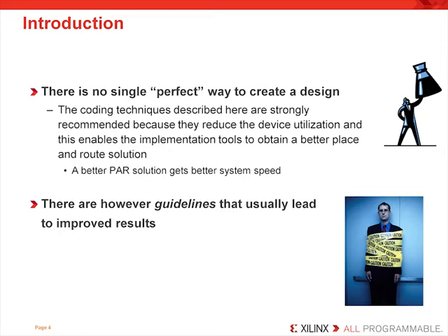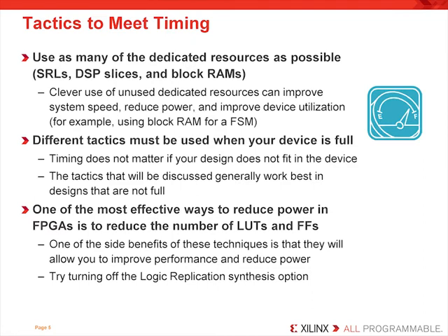And often designers waste a great deal of time resynthesizing and repeating a place and route solution over and over in hopes of meeting their timing objective. If you barely get your design to fit inside of the FPGA, the implementation tool's software options may not be as helpful as you'd like.